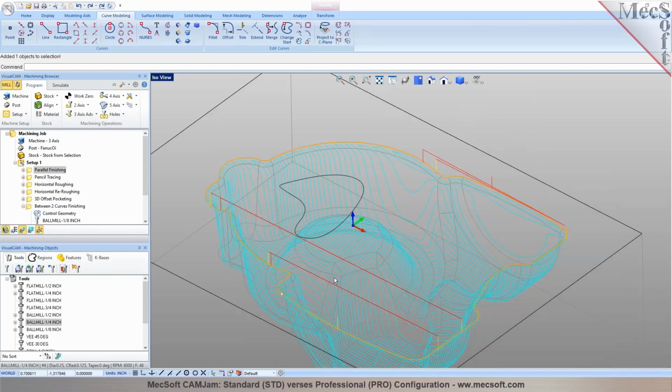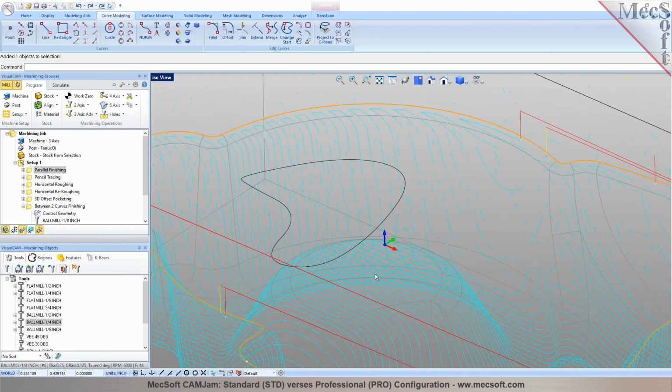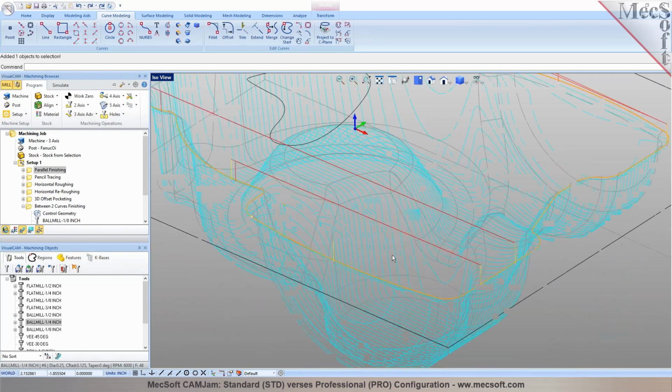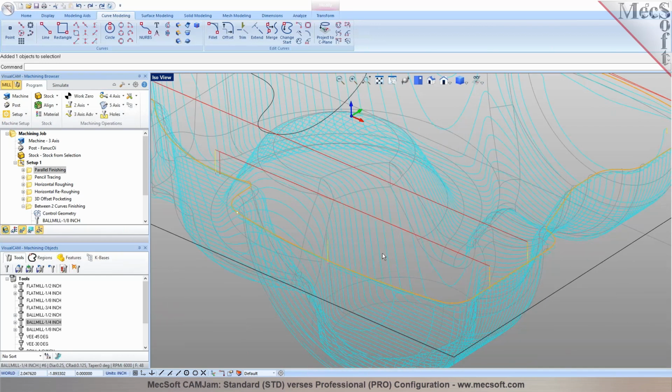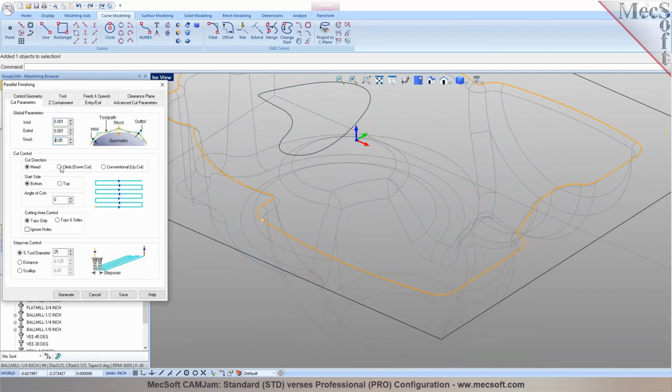If I go ahead and look at the wireframe view, you'll see that the cavity is now larger by 50 thousandths. Would that help? Yeah, no, that definitely helps. So if you leave a positive offset in here, it's going to stay off the part surface.